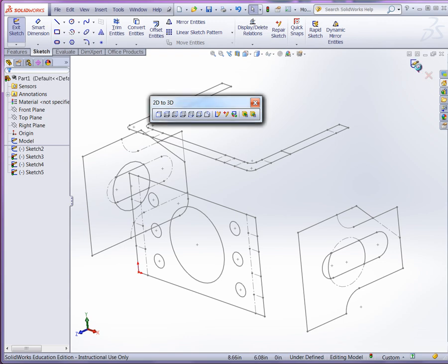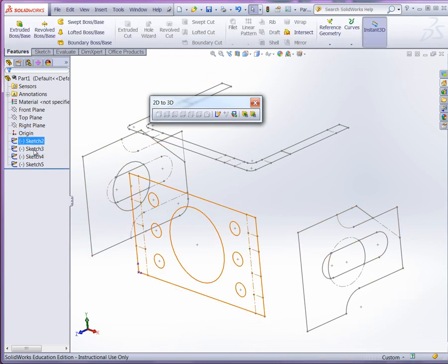Let's exit the model sketch. This is the information that was imported. Now, since everything is assigned to a new sketch and a new plane, it's gone, it's disappeared. As I hover over a sketch in the design tree, you can see the sketch lines in the drawing area that are selected. So if I click and do a long pause click, I can just rename it. I'll call this right sketch. Call this the left sketch. And I'll call this the top sketch.